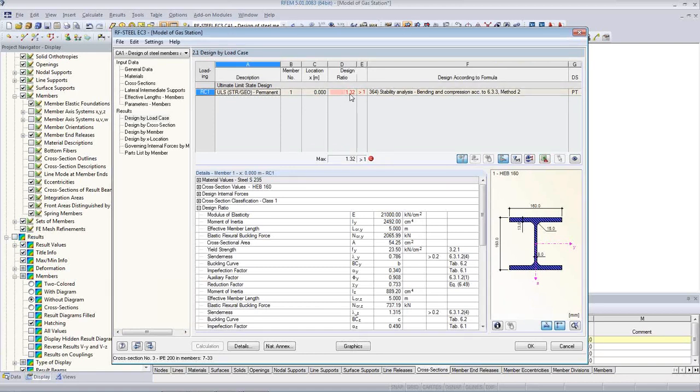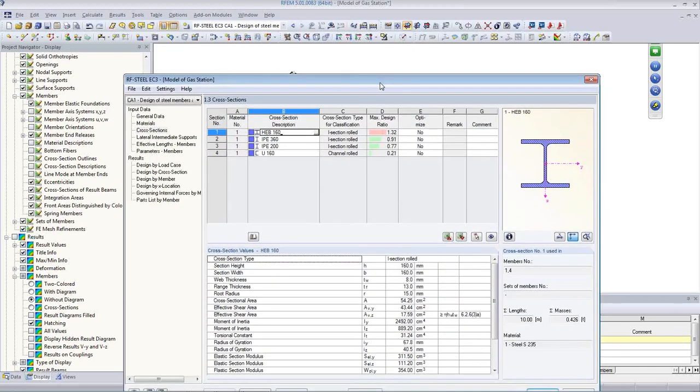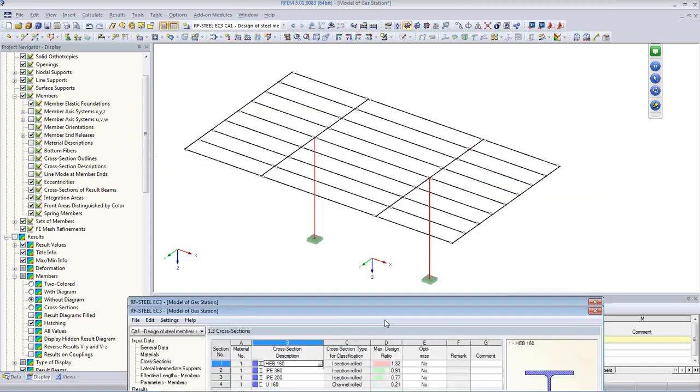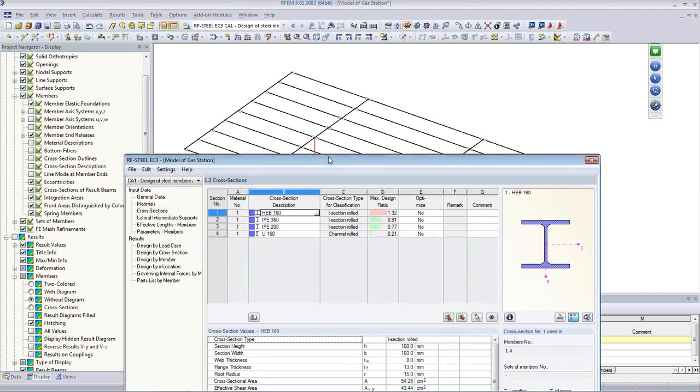We analyzed the optimized cross-section linearly, but we did a nonlinear analysis, so there are some things that are not quite linear, so here we have maybe to do another design round. I have not taken care of the serviceability and the deflections. And I know in these cases we have a problem with deflections, because if the columns are weak, the whole roof will kind of wiggle back and forth.